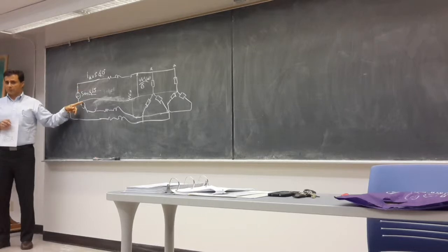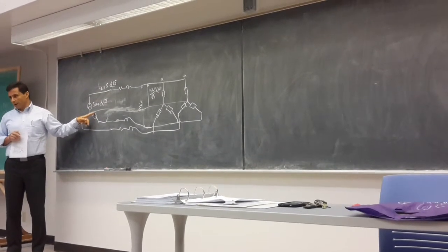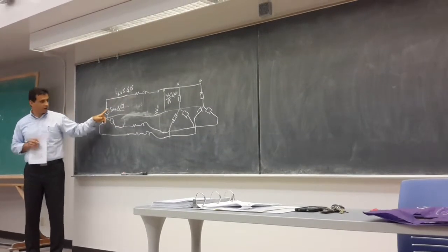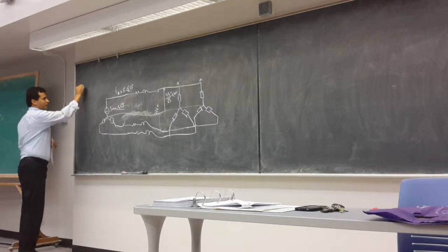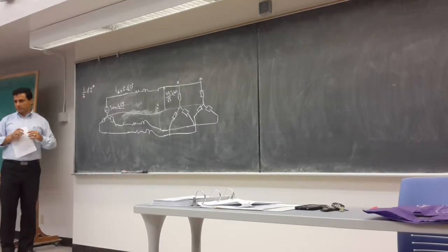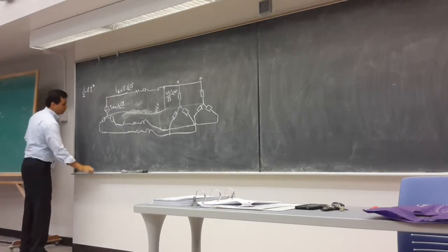these are RMS values. Remember the complex power was half of V I conjugate, right? We use the maximum values for the phasor, but these are the RMS values. What we said is half of VI conjugate for the complex power, but that one was the maximum value. So you can say either way.